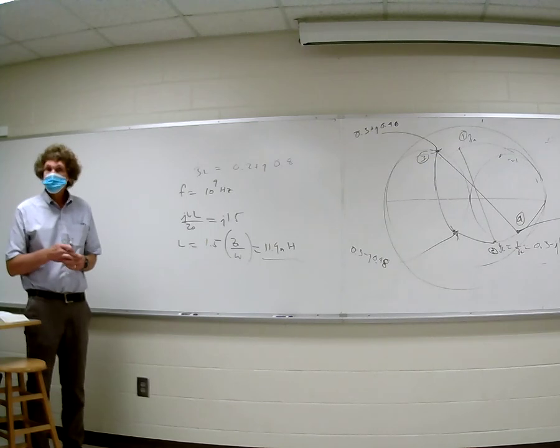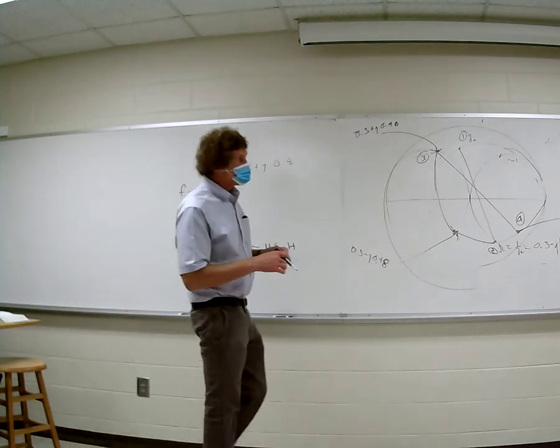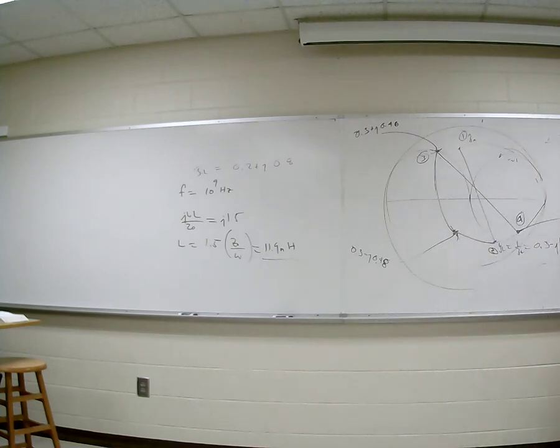You mentioned something about dodging the DC. What's that? Well, we want to make sure we allow DC biasing, because this load could be the base of a transistor. You all know BJT transistors require current to bias them, right? In order for that DC current to flow, you would want an inductor in series and a capacitor in parallel. If the inductor was in parallel, it shorts out the DC. Y'all follow me? So in general, when you're doing this stuff, inductor in series, capacitor in parallel, unless there's some overwhelming reason why you would want a capacitor in series. Generally speaking, you don't do that.